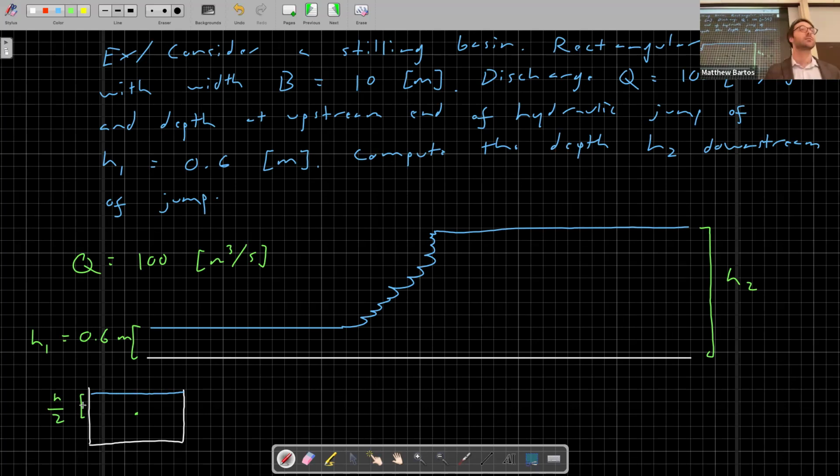But when you're just doing it with the hydrostatic, the centroid is actually lower because it was a triangle with like 2/3. That was the centroid of the triangle. This is just the centroid of the channel. So when you're analyzing the balance of moments, then you would need that centroid of the force triangle or pressure triangle. Here, it's just the centroid of the channel itself. A good question.